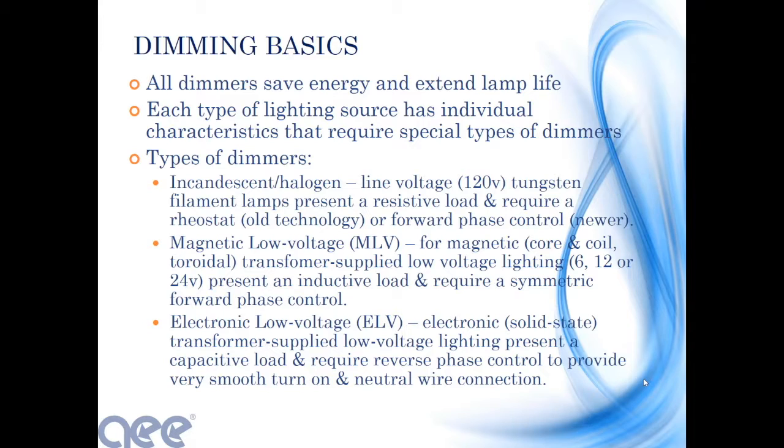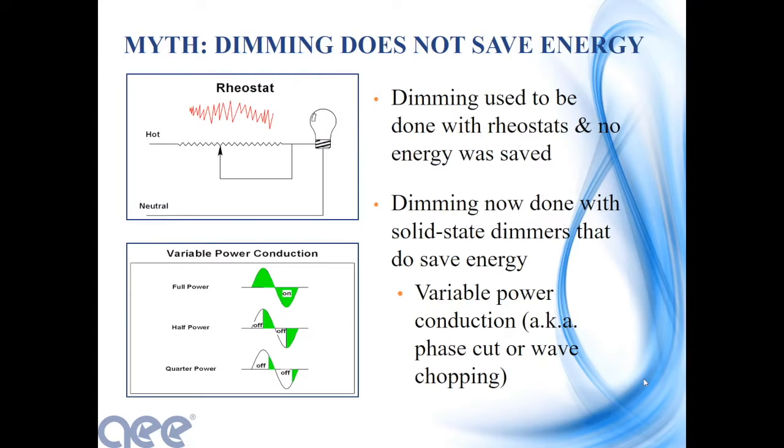Electronic low voltage, ELV, solid state transformer supplied low voltage lighting presents a capacitive load and requires reverse phase control to provide very smooth turn on and a neutral wire connection.